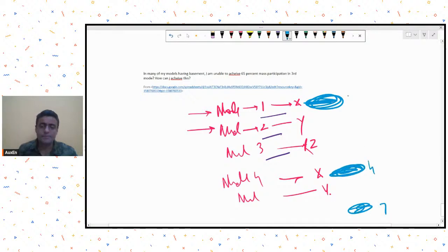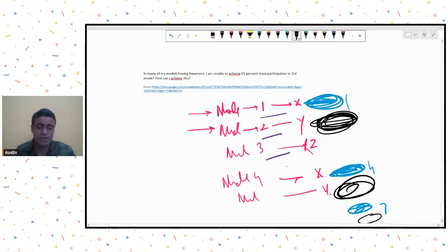Do you understand? Similarly, when I have to add masses for checking the Y direction, maybe I have to add the masses of second, fifth, and eighth. I don't have to add for the first three. It's not the first three numerically in the sequential numbers. It is the first three modes where there is a significant mass contribution. Do you understand this point? Okay. So you have to add up like that. That was the first point.